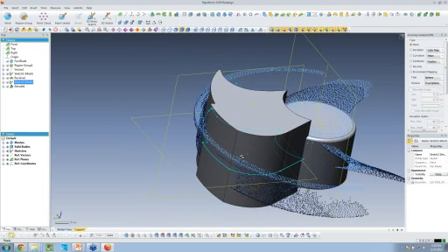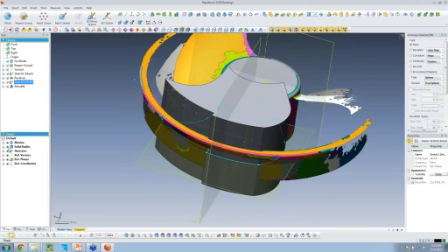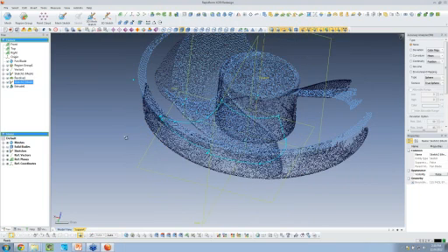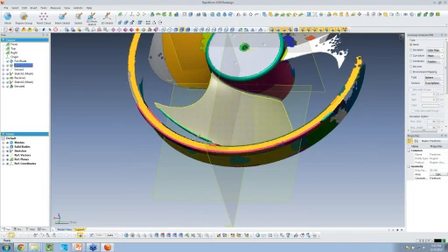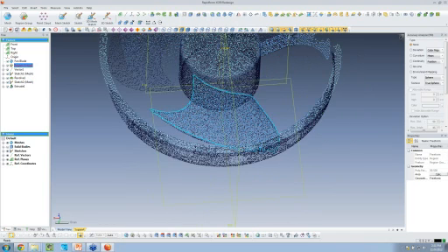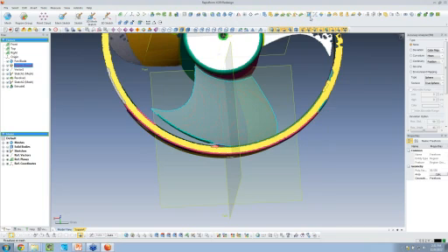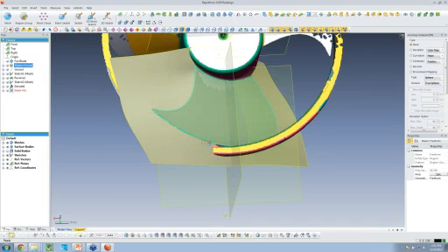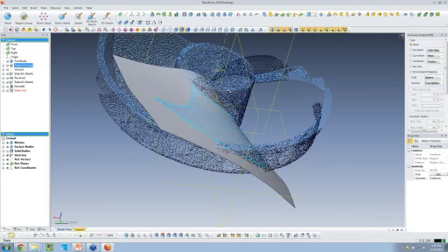And now I've got to create those faces. So let's suppress our solids for now. Let's talk about making freeform faces. This is the important feature for me now. We have a tool that's called Mesh Fit. Mesh Fit is going to real quickly create a surface model of that face. Basically, it vacuum forms that plane down to the planar feature and makes a nice freeform surface for us.